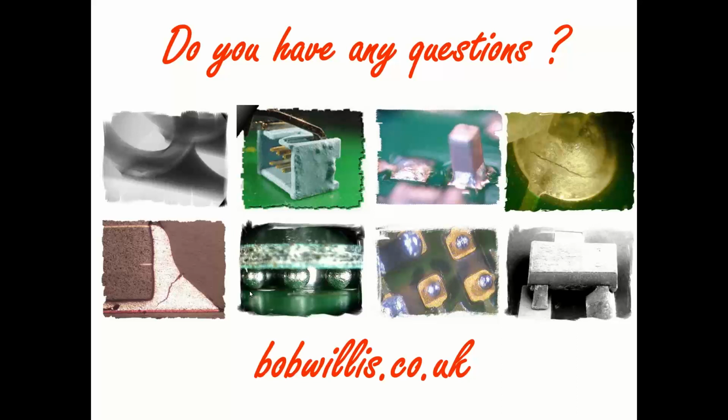A classic example, if I may, is if you take a printed circuit board that you know works, you can power it up and immerse it in water or a salt solution. You won't find attack on other surfaces. It will just be at the interfaces between the joints, the solder, the pad terminations, and that's where you'll see all the reaction take place.